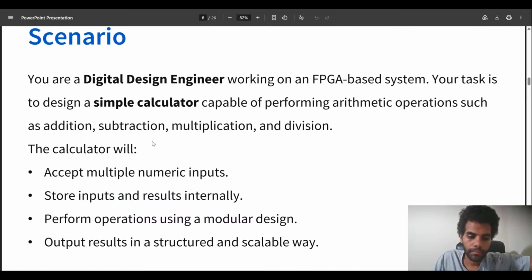So again, one module would be the FIFO, the other module would be the ALU, and then we just show the result. The ALU is very easy because you're simply receiving the numbers as integers, and then you have a switch case. I even made it here: operand one, operand two, and operator, and there must be a switch case in order to switch between the different operators and then produce the result.